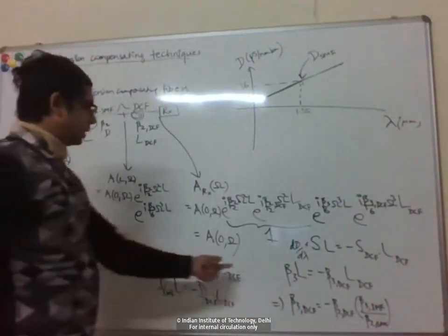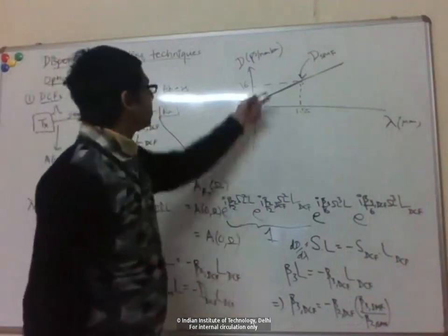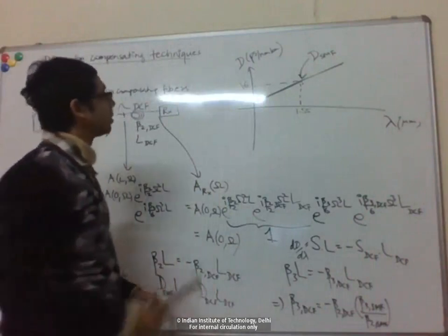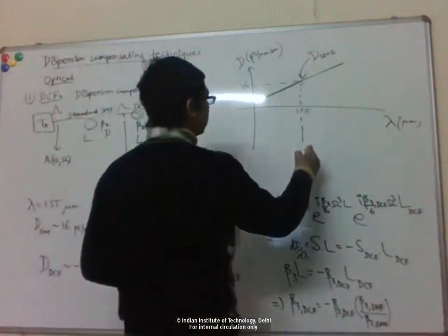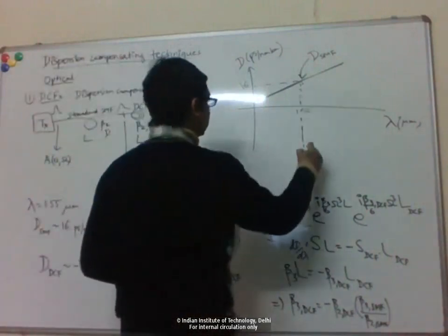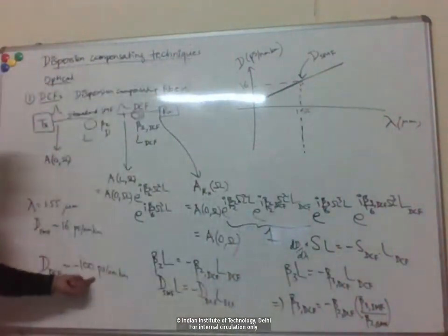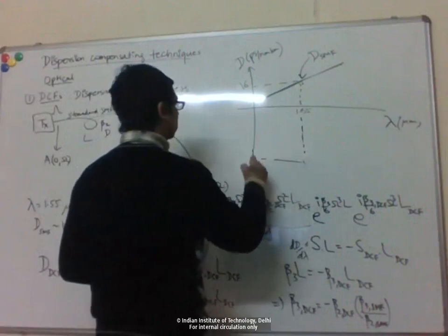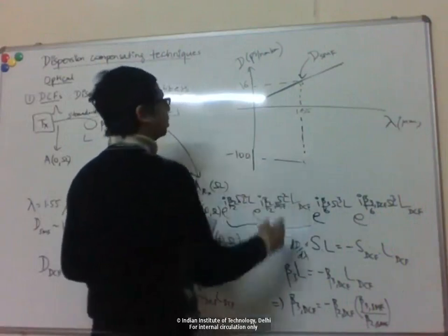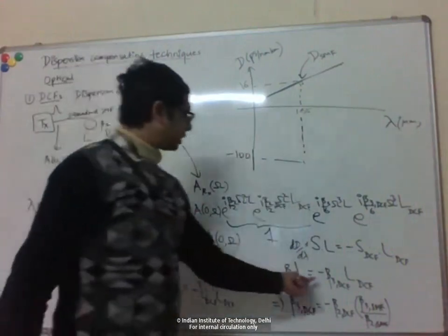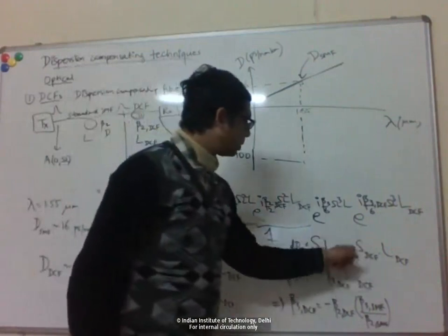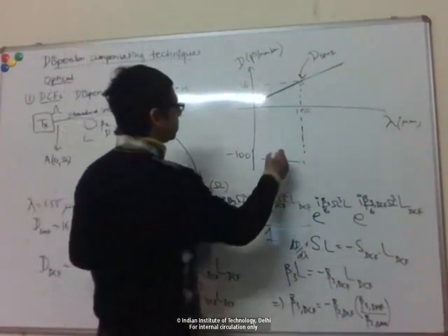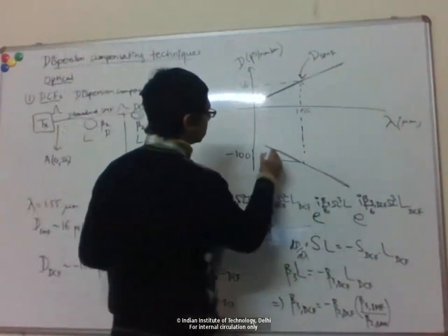Now, so if we use a dispersion compensating fiber, right, which has this condition, so it has an opposite sign for D, right? So let's say at 1.55 we do that. So 16, let's say, for example, this one has minus 100. Right? But also it satisfies this condition, right? So the slope is negative of the standard fiber, so the slope is like this.